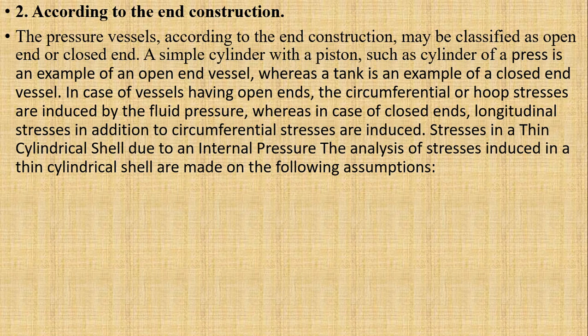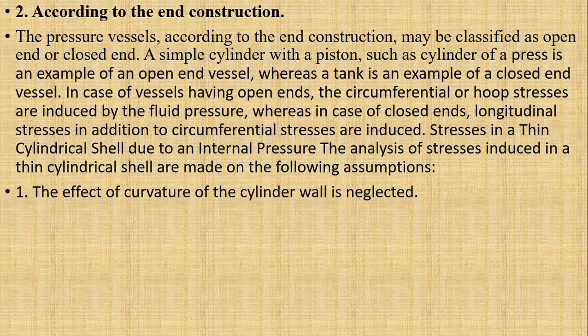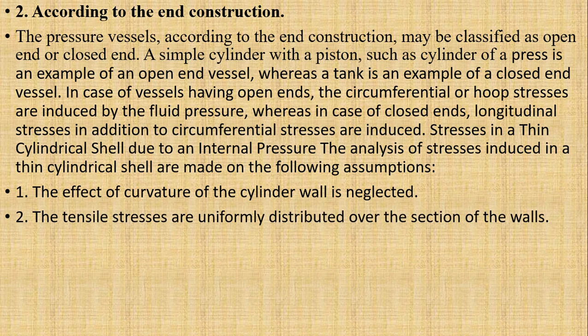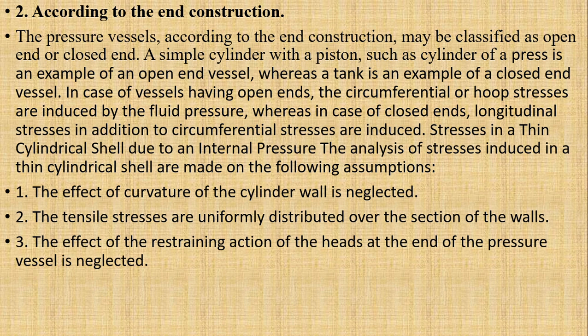Induced stresses in a thin cylindrical shell due to an internal pressure. The analysis of stresses induced in a thin cylindrical shell is made on the following assumptions. First, the effect of curvature of the cylinder wall is neglected. Second, the tensile stresses are uniformly distributed over the section of the walls. Third, the effect of the restraining action of the heads at the end of the pressure vessel is neglected.